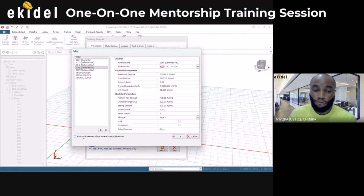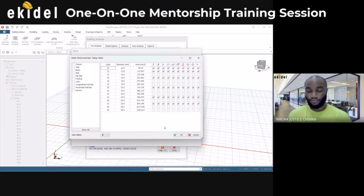Okay, that's fine. So now also choose here to apply to all members, and then don't just say okay yet. You can see it says edit rebar diameter. Edit. You can choose the size of your reinforcement for column and for beam. You can just assume it first. So I click here that says edit.